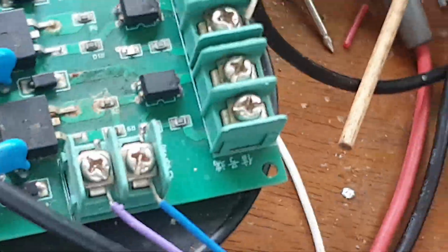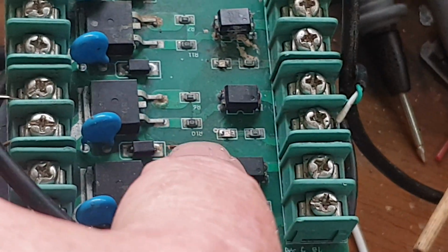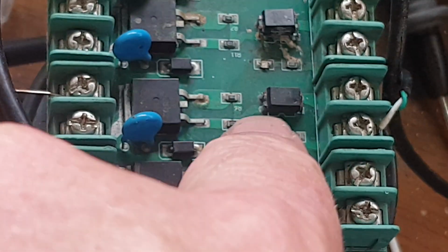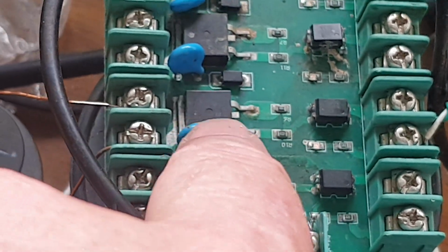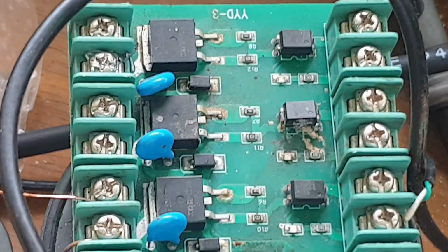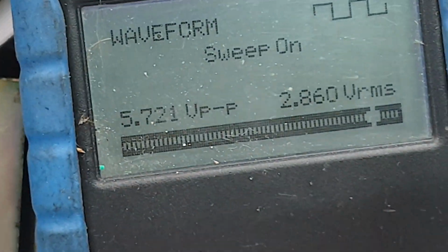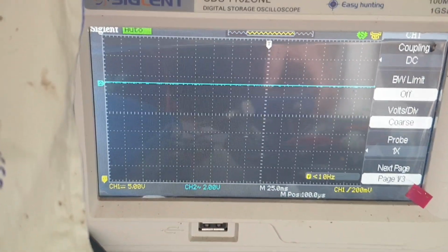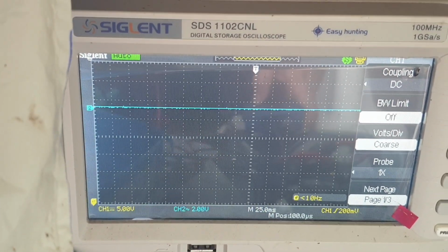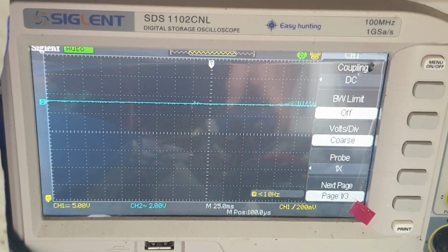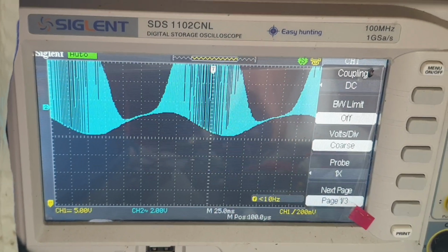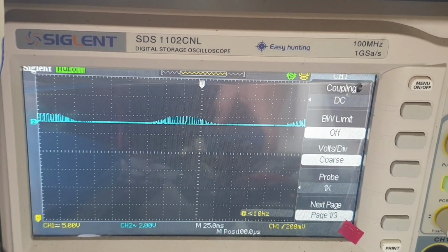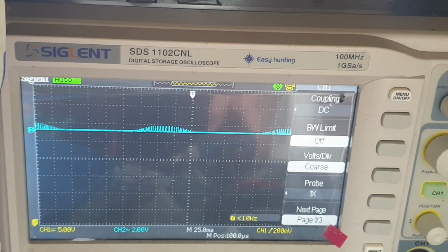So that's an indication of how much signal strength is going across this optocoupler and whether or not the FET is switching. So right now it's not. You can see it's down here like that, 2.8 volts. Okay, so I'm just going to start sneaking up the size of this signal. There we go, look at that. So I'll come back a bit. See how I've just got a bit of a mohawk starting, but that's above the line.